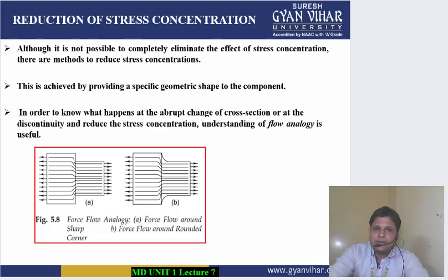There is a similarity between velocity distribution in a fluid flow in a channel and the stress distribution in an axially loaded plate. The equations of flow potential in fluid mechanics and stress potential in solid mechanics are more or less the same. Therefore, it is perfectly logical to use fluid analogy to understand the phenomenon of stress concentration.